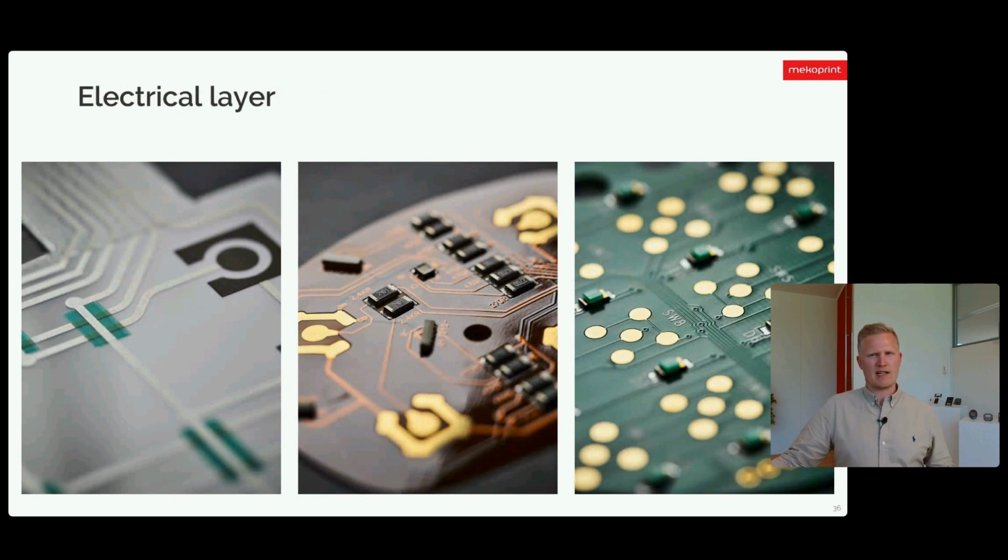When it comes to choosing the electrical layer, both the environment, electrical and mechanical design concepts can affect the choice. Polyester with printed silver is the most commonly used electrical layer for a keypad, as it is cost effective, but it also has a limitation. When it comes to how much you can bend the silver traces, normally we do not recommend to bend the silver tail more than a radius of a pencil. PET also has its limitations when it comes to moist environments. So it is important to weigh the pros and cons for your specific project.